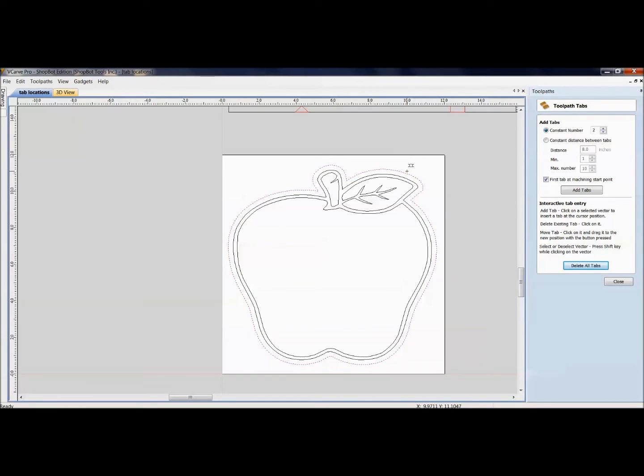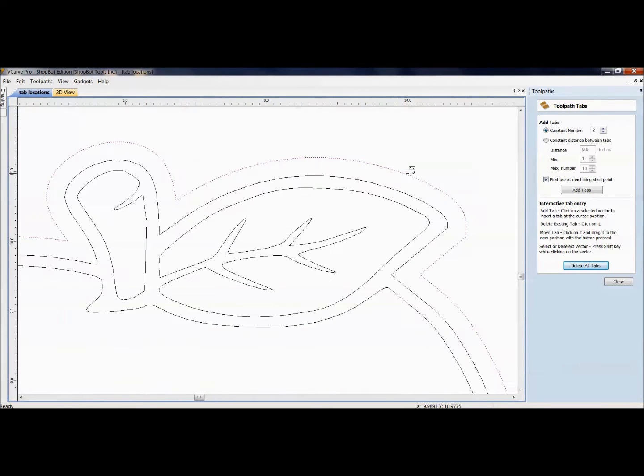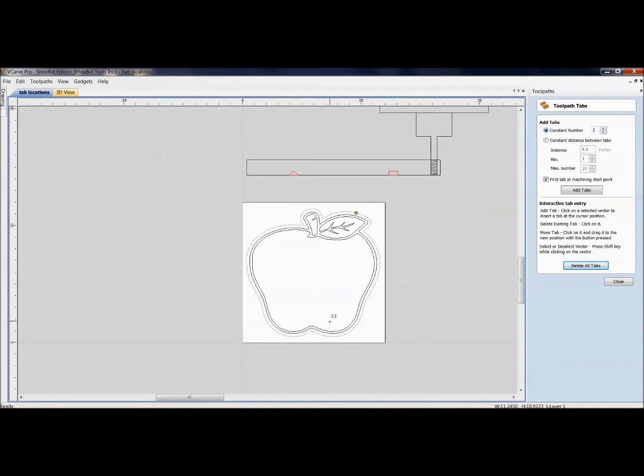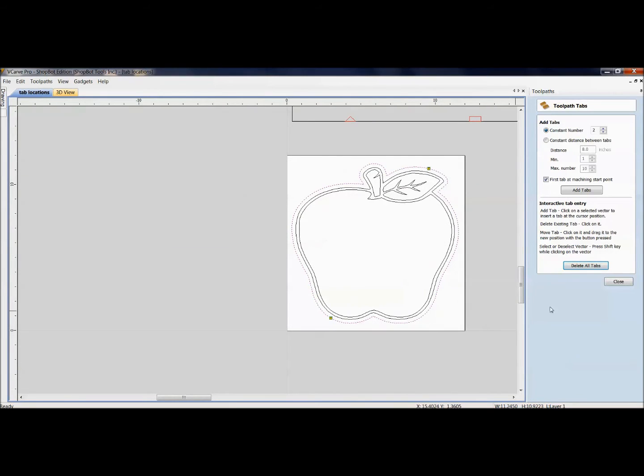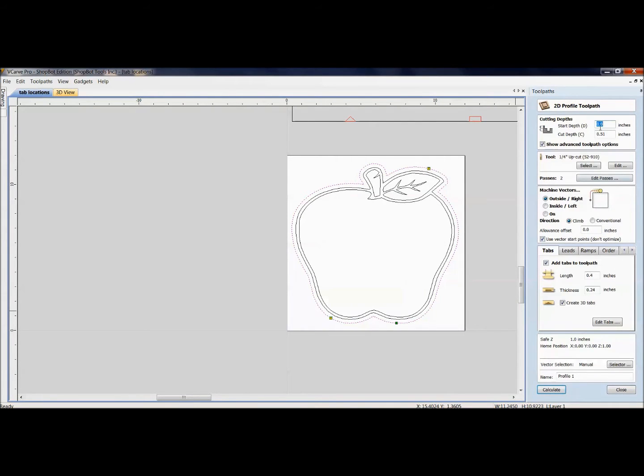I know I've got a little disc sander and spindle sander over here that I could use to get to these outside curves really easily. So I'm just going to put 2 tabs opposing each other, and that would be enough for this project, just cutting it out of thin plywood. So take into account the grain of the wood. It's nice to have a tab going with the grain. It's easier to nip out.